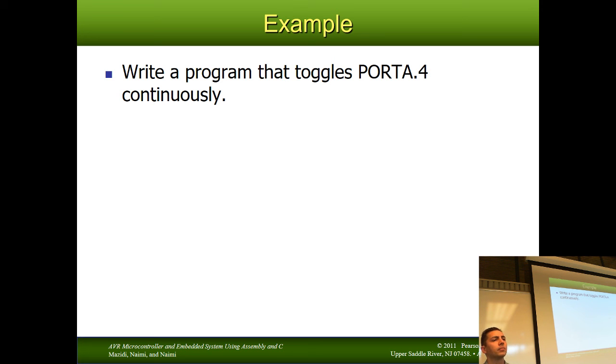All right. So at the high level, there's really only two things you need to do. First, you need to make sure that DDRA bit 4 is a 1. So you need to write that bit. And then you can just go back and forth setting that bit and clearing that bit.